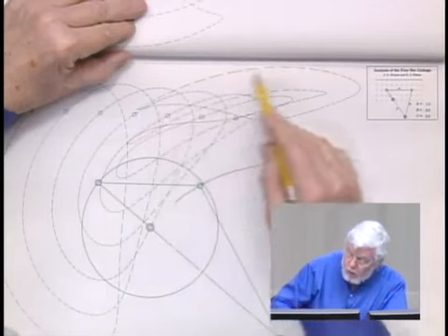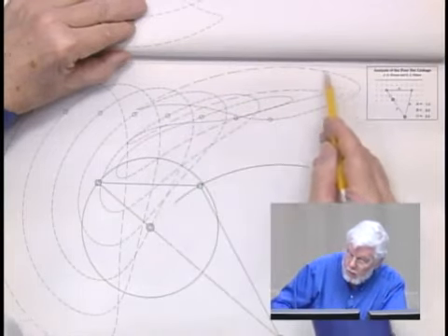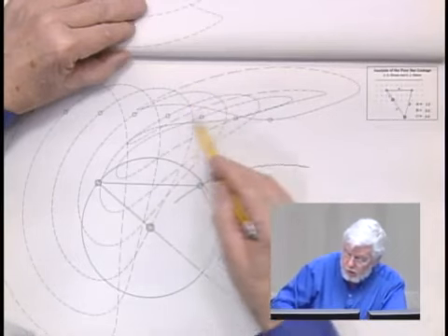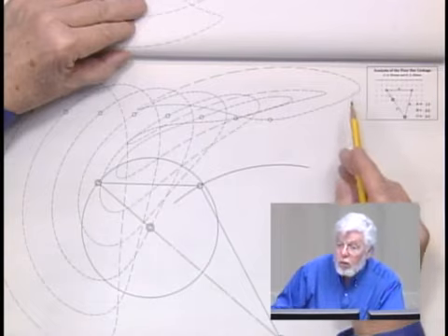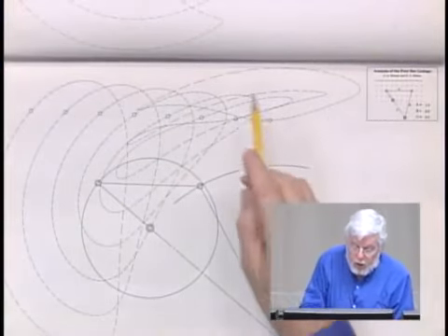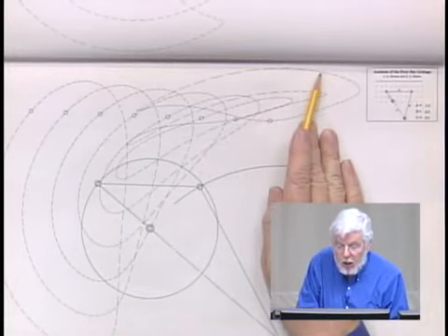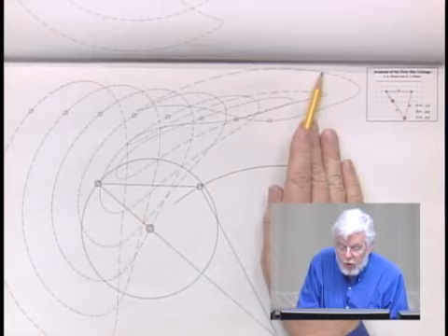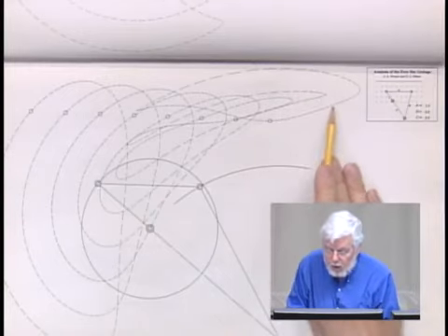So if you look at the curve that I just chose, and you look at the relative lengths of the dashes on the back side here versus down here, I can impute a lot about the velocity of that point. For one thing, it's going faster on the backside than it is here, because for the same delta time, which is to say delta angle of the crank at constant speed, I'm moving about 3 times as far as I am down here.